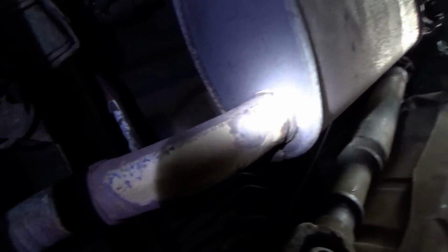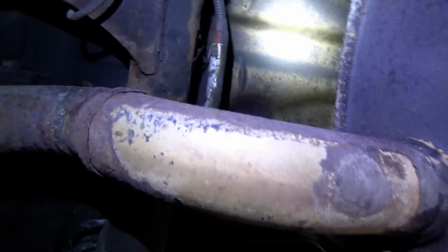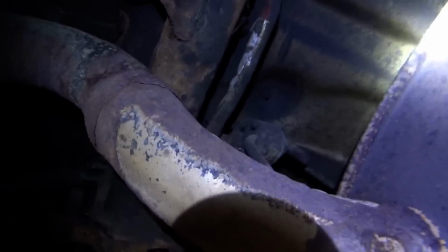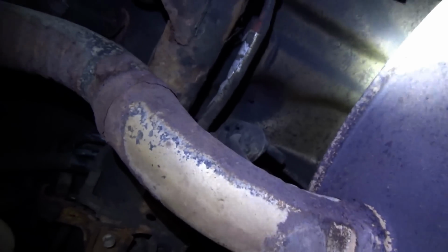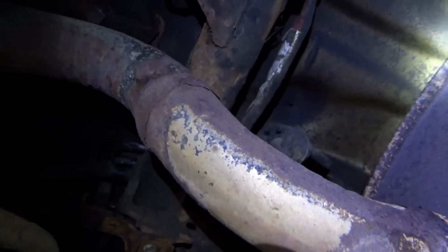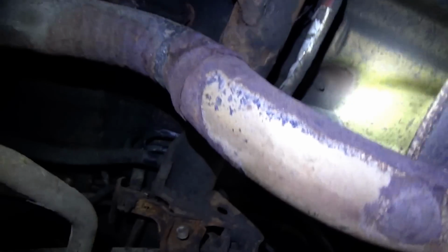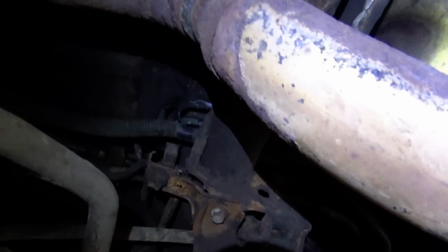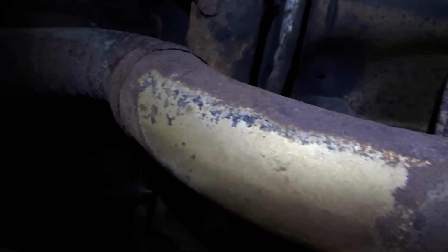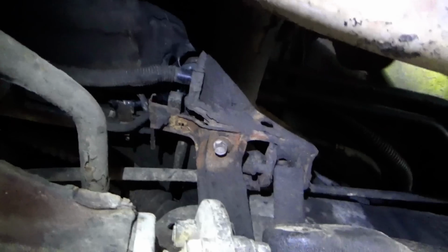That's a mess. Well, let me inspect that plastic pipe. This is hilarious. So the flange broke off on both sides. Okay, but the tailpipe actually fits over the remains of the elbow. Kind of. It's rusty, but at least temporarily this will work in keeping the hot exhaust gases from causing carnage under the truck. So we can put a little clamp on here just to keep it in place.